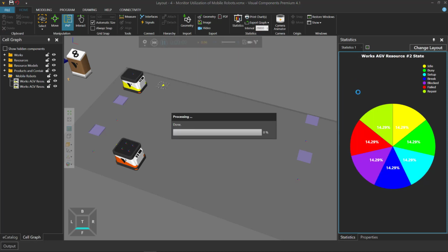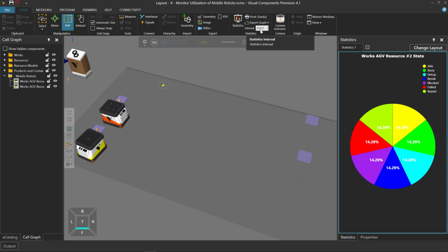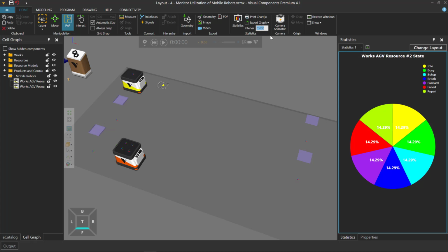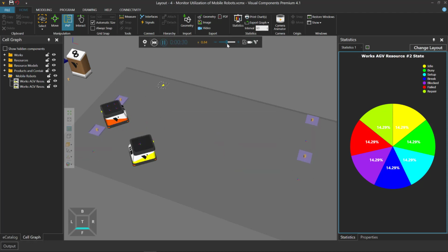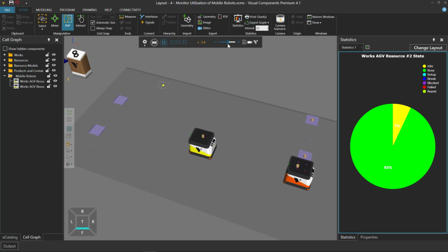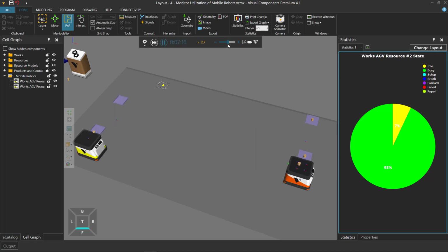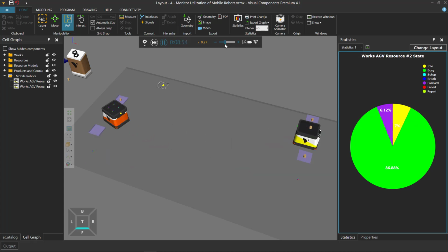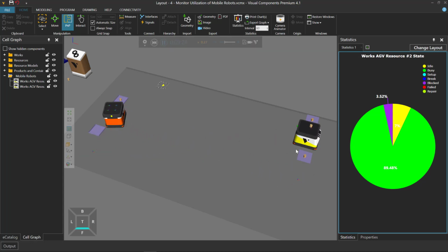And what I'm hoping to see is when I'll get a block state for this resource. And we're not going to see that because I didn't change the global sampling interval here for the chart. So we'll still have to wait 8 hours. I don't want that. So let's change this back to 60 seconds, and run our simulation. Okay, so it's not blocked yet. Just trying to see maybe within the first 10 minutes we can get an idea of what's happening. And yep, we got it there. So that was around 7 minutes, and it seems like they're getting blocked a bit here, going to and from.